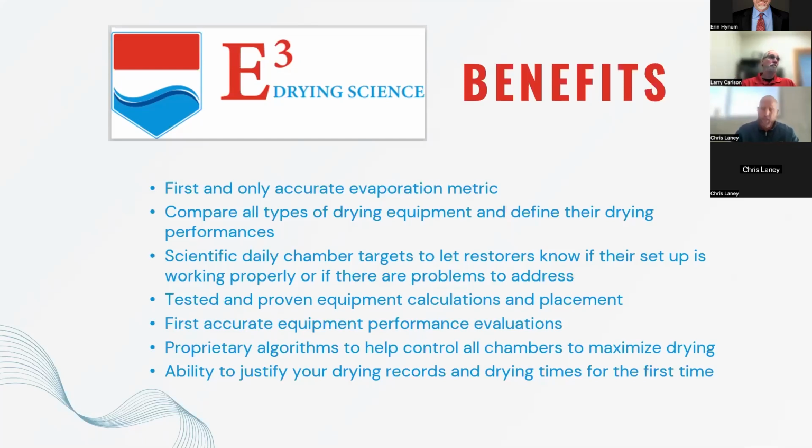And then we're ultimately going to evaluate those dehumidifiers. We can evaluate those desiccants to say, are they performing properly? Do we need to pivot and make a change or swap that equipment out? And then when we look at being able to justify our drying logs, one of the biggest challenges is how long did that job take to dry?